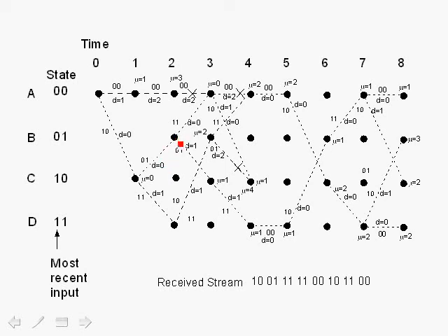If we continue at this node, if we get, for example, a 0, we go down here, and if we get a 1, we go back to the state 1, 0. Consider this situation here. For the 0, we go back to state 0, and we output a 1, 1. Compare that with the received sequence 1, 1. The Hamming distance is 0, so we label that.